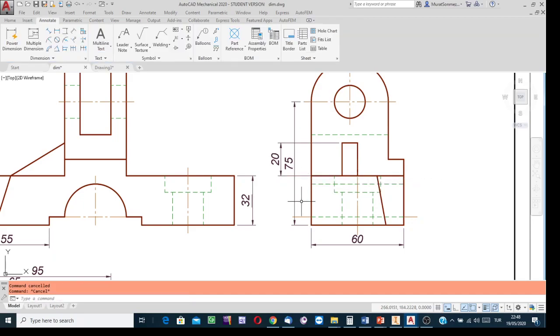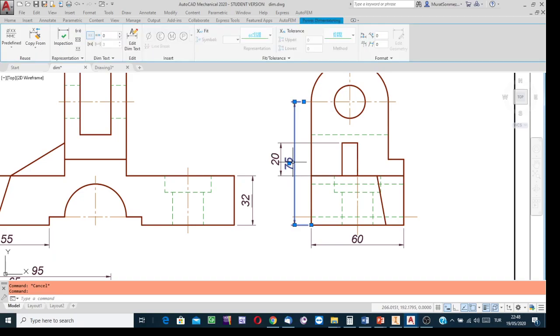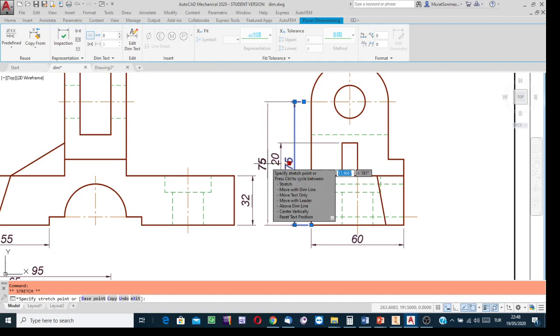What can you do? If you forgot to show a smaller distance first, what can you do? Well, don't be in a panic. First make a click on the dimension it is in a greater size. After the click, you find the gripping point just on the dimension. Hold this gripping point and then slide. You can make the distance greater.